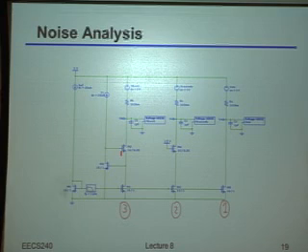So let's take a quick poll. If I compare the noise coming from current source number 2 versus current source number 1, who thinks current source number 2 has less noise? Same noise? More noise? Okay, so that is technically correct. But now let me ask you, a little bit more nitpicky: how much more noise is it? Is it a lot? Or is there a little bit more? A little bit. Okay, so for the people who said a little bit, why is it just a little bit more?